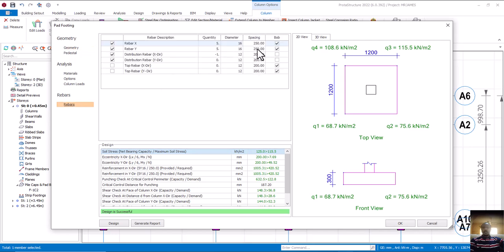My reinforcement is okay. You need to check your reinforcement, because if you do not choose your reinforcement properly, it can go ahead and use Y20 or Y25 or even Y30 to design your foundation. That is why that general settings during design matter. I think we have done a video on that. Still go and watch the other ones we have done. I've done settings on how to do your settings after you have finished your modeling. Is that okay? Edit of your materials, yes. So we have done that very well.